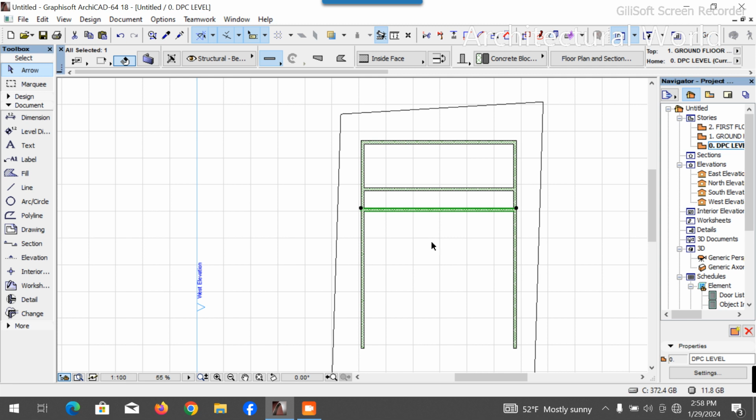What do I need? I need the staircase room. Now, what am I going to give the staircase in width? I'm going to give the staircase a width of, let's say, 2.4 meters, since it's a residential building. If I add my 225 millimeters to it, that's 2625 millimeters.